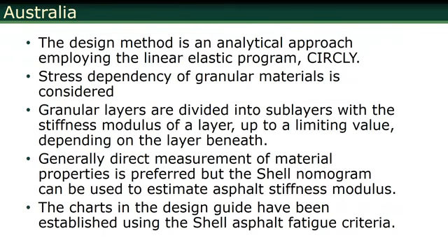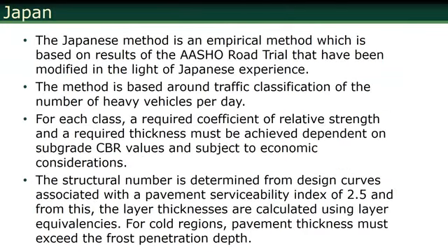So you can simulate the structure with increasing modulus. Generally, direct measurement of a material property is preferred, but Shell nomogram can be used to estimate asphalt stiffness modulus. And the charts in the design guide have been established using the Shell asphalt fatigue criteria. So their software is based on the Shell method. I'll talk about the Shell method a little bit because the pavement ME uses something somewhat similar.